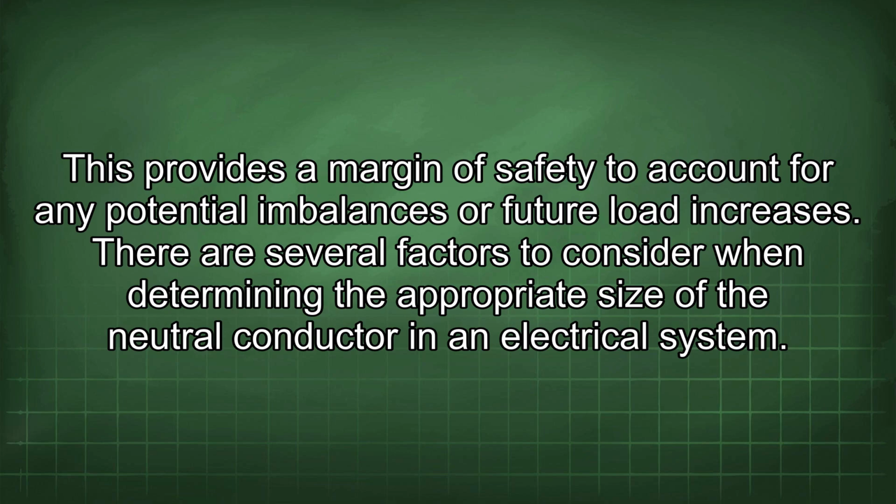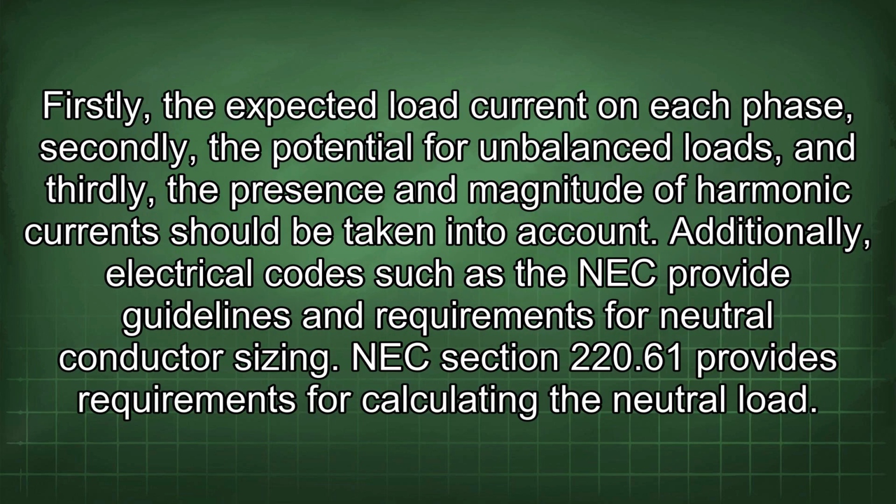There are several factors to consider when determining the appropriate size of the neutral conductor in an electrical system. Firstly, the expected load current on each phase. Secondly, the potential for unbalanced loads. And thirdly, the presence and magnitude of harmonic currents should be taken into account. Additionally, electrical codes such as the NEC provide guidelines and requirements for neutral conductor sizing.